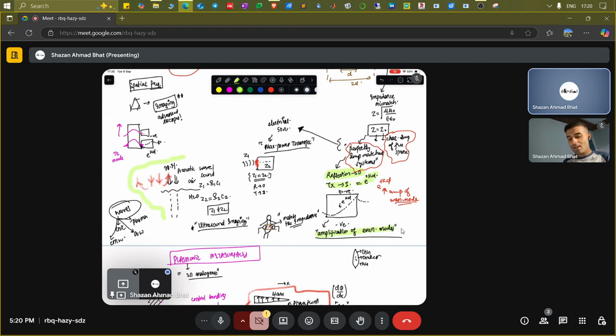I talked about here this concept of acoustic impedance mismatch, which happens to be a universal concept, whether it's electrical, thermal, mechanical, optical systems, or any systems. These happen to be a universal concept because they are all related to the concept of waves. So if you have incoming acoustic waves over the water surface, let's say, then most of it is going to get reflected because the acoustic impedance mismatch is huge, where the acoustic impedance is given by the product of the density of the medium times the speed of sound in that particular system.